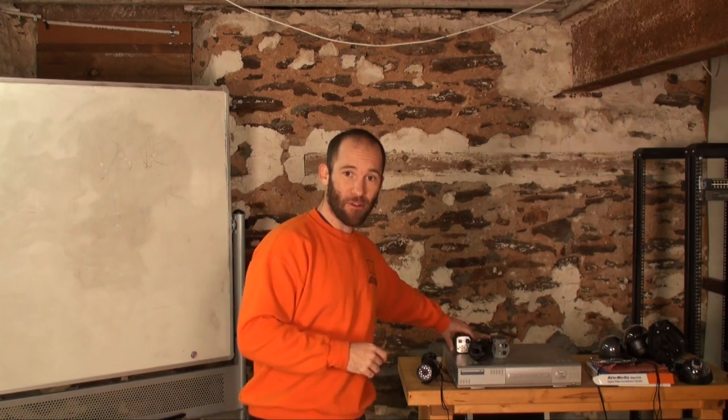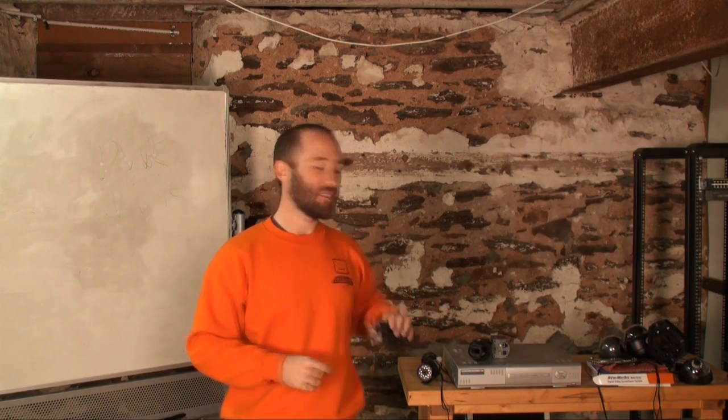Then there was resolution. Remember, with analog cameras, we're dealing with TVL, TV lines. These are the horizontal lines on a normal old TV, a cathode ray tube that probably nobody has anymore. 600 TVL is approximately, don't beat me up if you're an actual surveillance guy, approximately DVD quality. And again, it ain't as good as you think it is. And then it goes all the way down to about 320 TVL, which is low quality. Basically, you see the blob moving across the room.